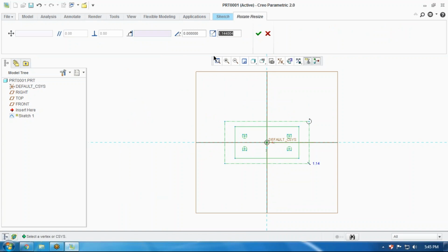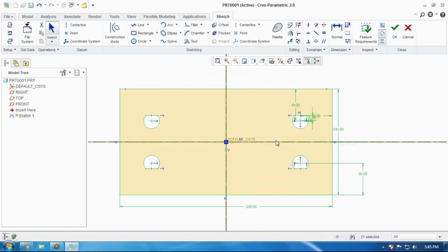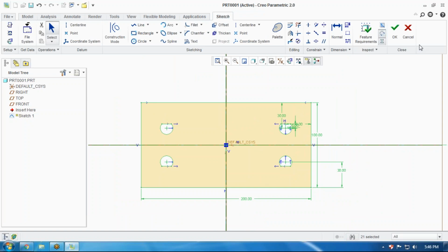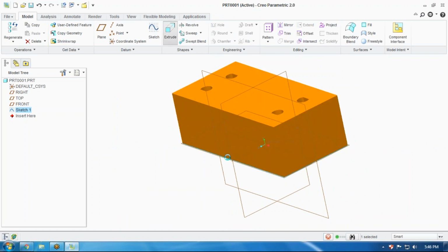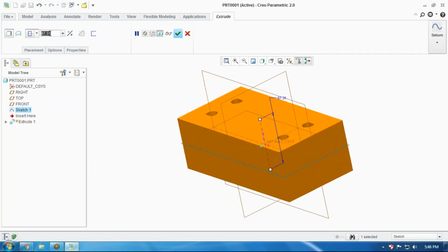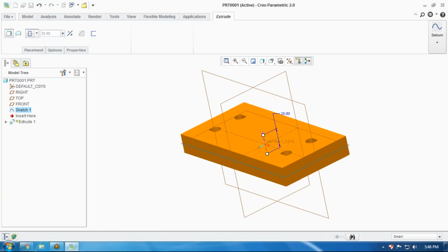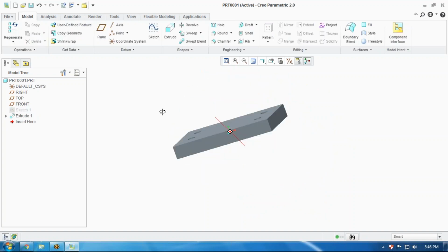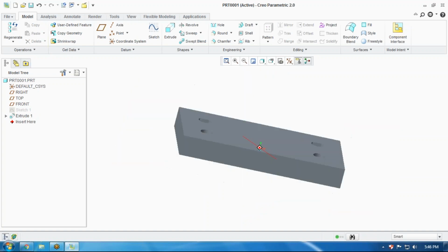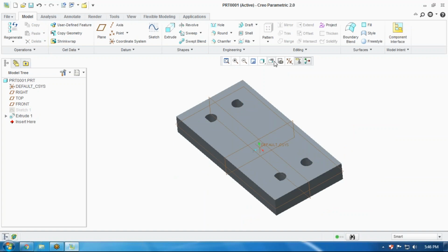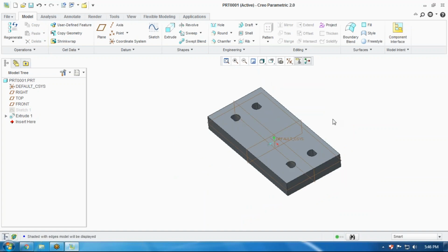Now put the cursor on the screen and now put this like. Now there is a ratio. I'm just giving the scaling ratio as 1, then all parameters will be the same. Click update, then you can see there all the dimensions have been given the same. If I'm just giving the parameter double, then all parameters will be increased. Now you can see that the object has been got. Now make an extrusion there, and now we'll see there we are making a mirror section. 25 is the value we have just defined, and now we can see this has been created like this. The object has been created simply, right? So by this way we can create the solid sections as per our need.